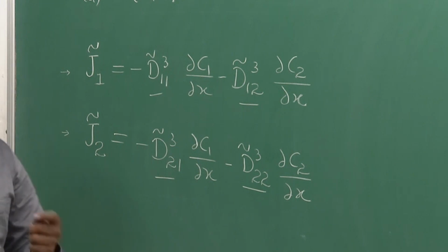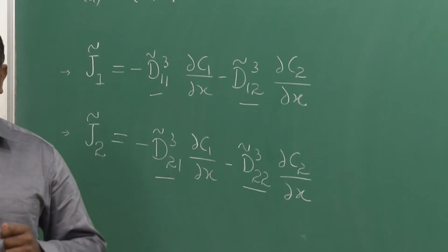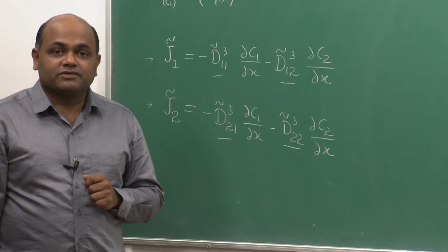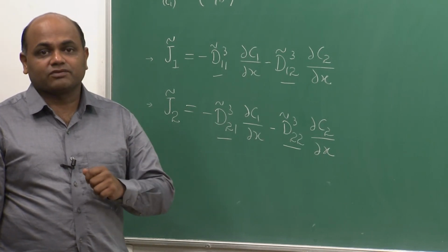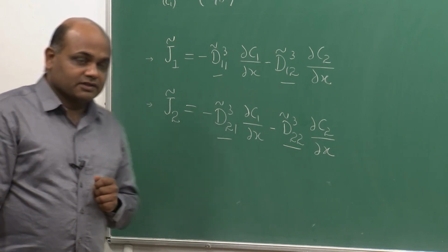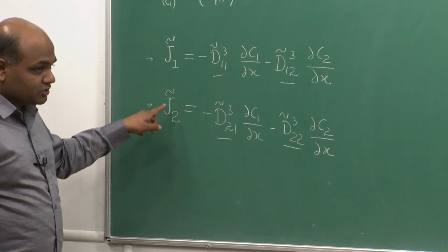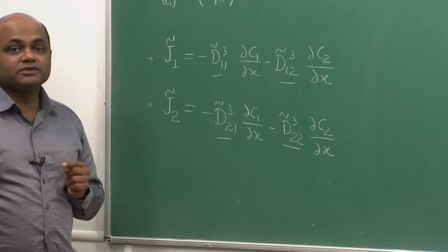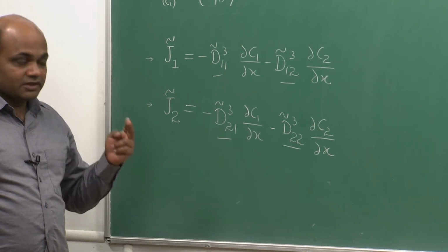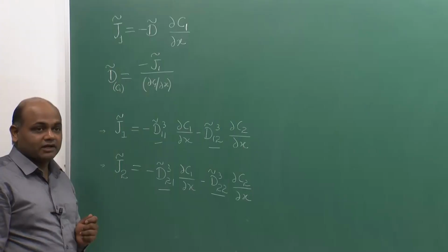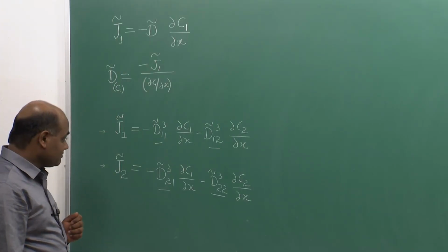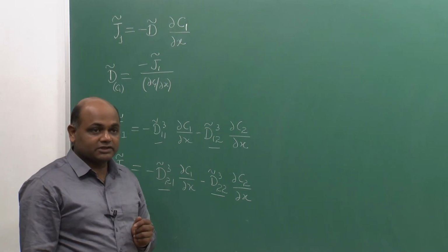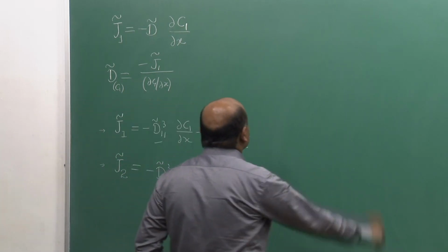So, obviously, I need more than one diffusion couple, and since these interdiffusion coefficients are functions of composition, we want to make sure that there will be a common composition in the diffusion zones of the independent diffusion couples that we assemble. So, Kirkaldy had proposed originally this approach. So, let us call it Kirkaldy's approach.